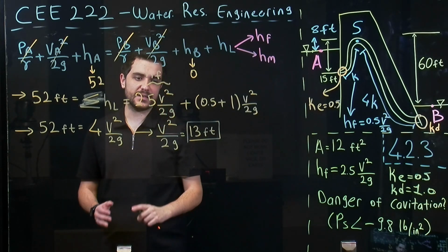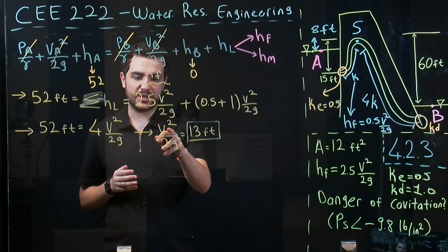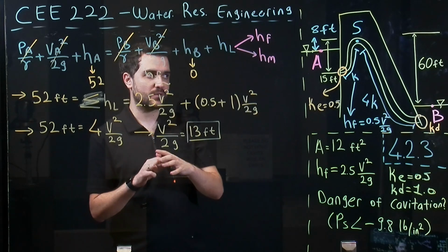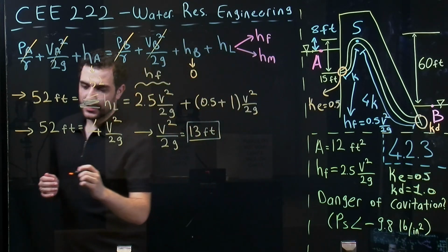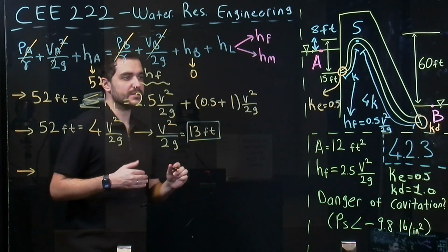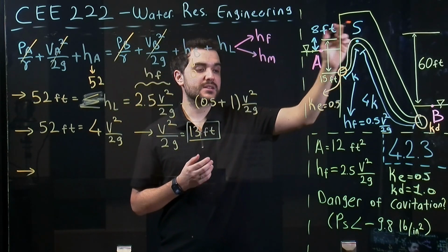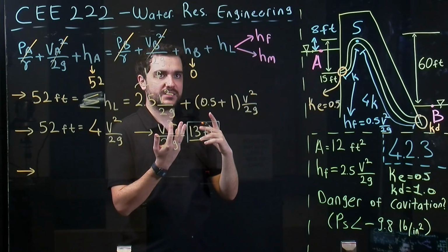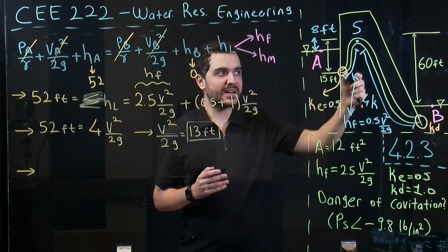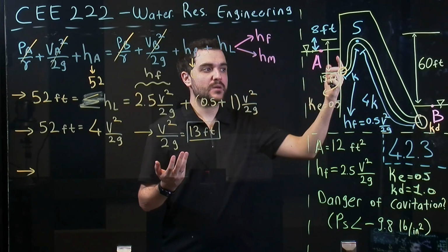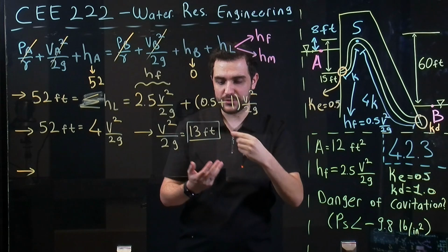So this is an important step of this question, because we know the velocity head right now, and we can get velocity using this value. The most important thing to find here is the pressure at this point, so that we can actually write an energy equation between point A and point S. Because we don't need the other remaining parts, we will need only these pipes' values.